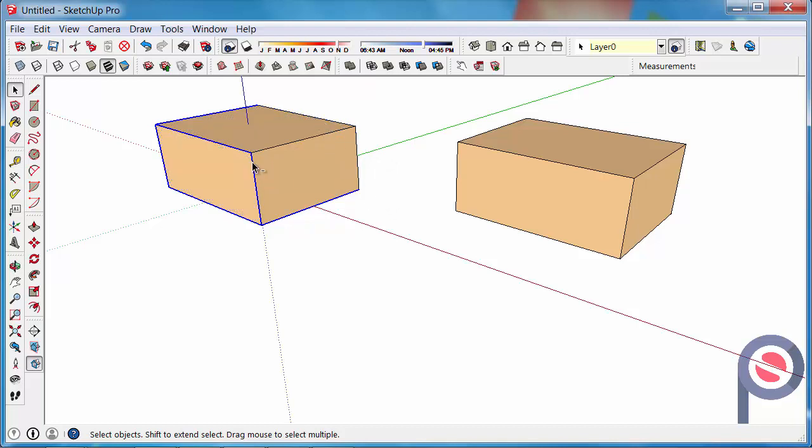And if I keep going, I could deselect the whole thing. If I hold Control, it gives me just the plus. So I can then add only to the selection. So I'm picking up elements that I want to select, and I can just carry on adding. So why you might add and subtract selections is because you might think to yourself, I only want to delete this part of the model, leaving behind the rest of it. So I would select it and delete it.